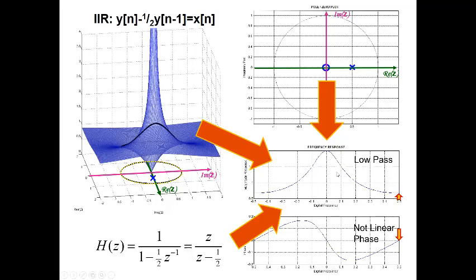So as you can surmise, if we want bumps in our magnitude response, if we want to push it up, we're going to need some poles nearby. If we want to push it down to give some attenuation, we're going to need some zeros nearby. We'll go into a more sophisticated way of looking at it than that, but that's the idea.